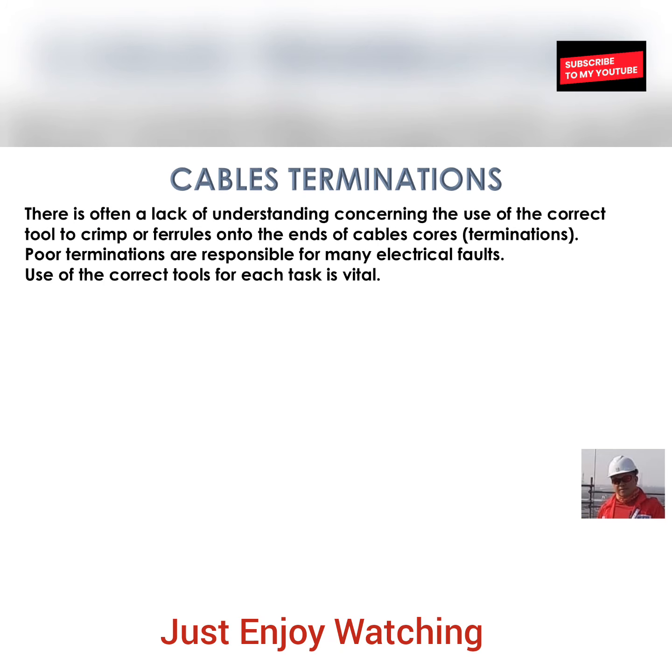So cable terminations, there is often a lack of understanding concerning the use of the correct tool to crimp or press onto the ends of cable core terminations. Poor terminations are responsible for many electrical faults. Use of the correct tools for each task is vital. That's why it's very important, guys. The technicians or the cable terminators, we need them certified. They have a certificate to do especially high voltage terminations and low voltage terminations.